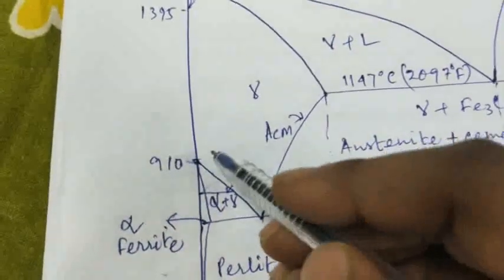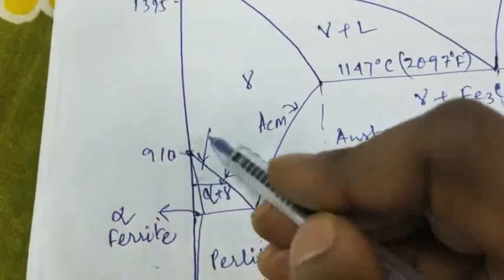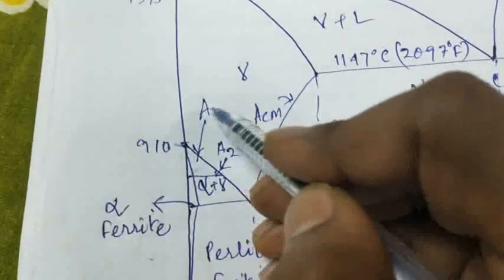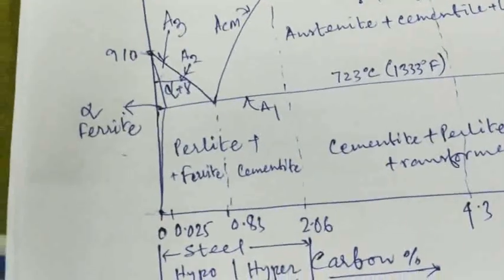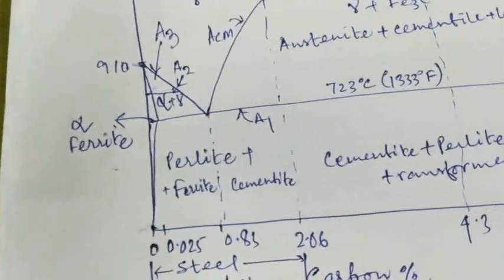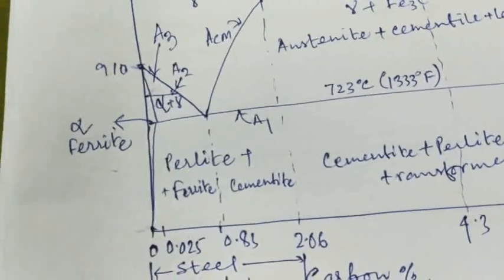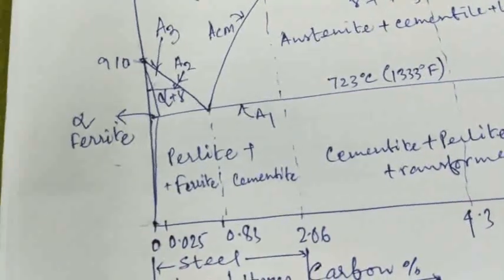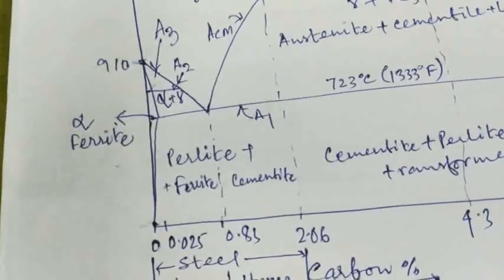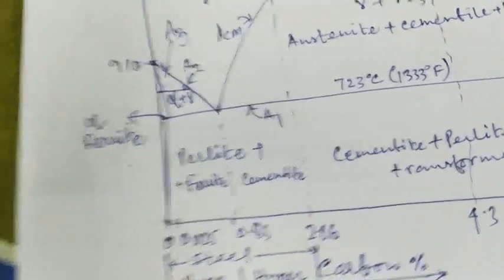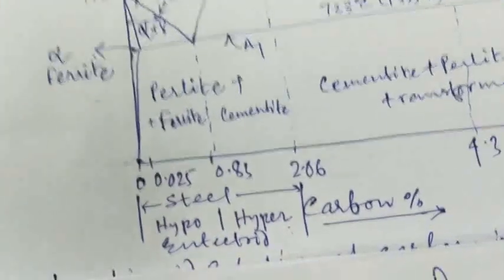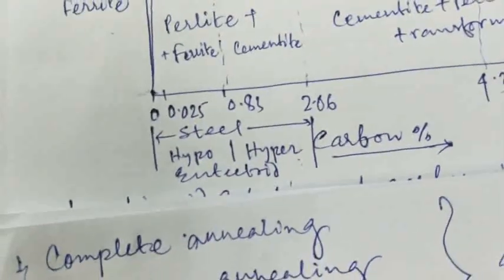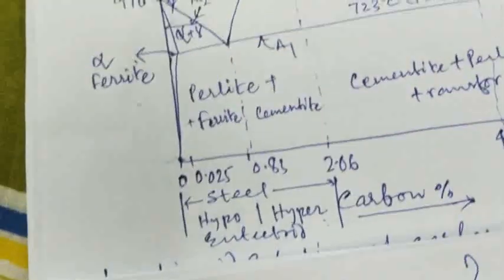In the iron carbon phase transformation diagram, this is actually the AC3 or A3 line. So heat the steel above the A3 line by 20 to 30 degrees centigrade, preserve the heat for a period of time, then cool slowly along with the furnace to get closer to the balance of the heat treatment process. Completely austenitizing.